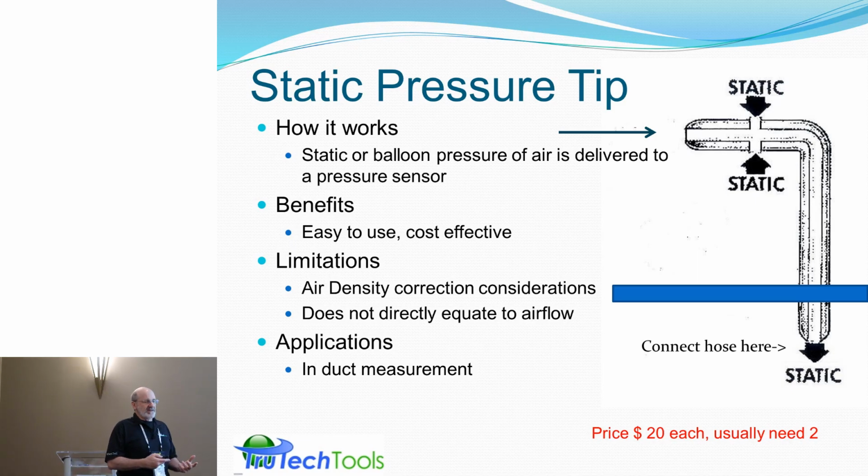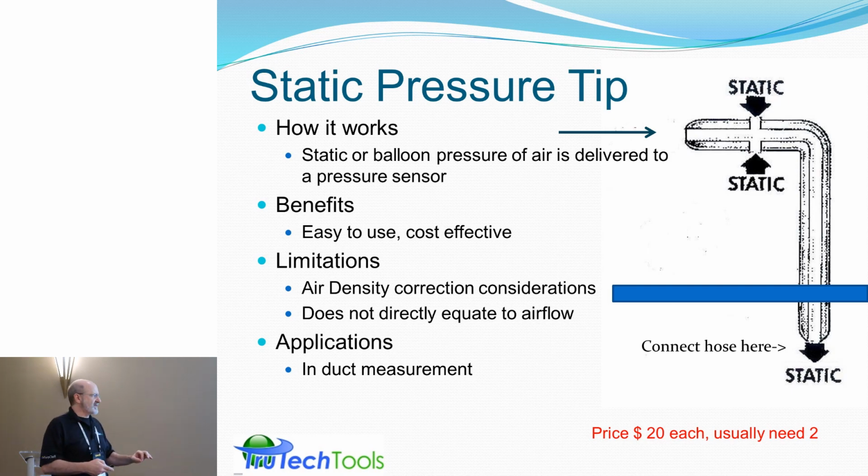So they're pretty easy to use, pretty cost effective. I think we sell them for like $14 each, around that or so. You do need a manometer to get the reading out of them, but they don't directly equate to airflow. You need to know another step in between, that airflow chart, and we'll go through one of those, an example, in a moment.